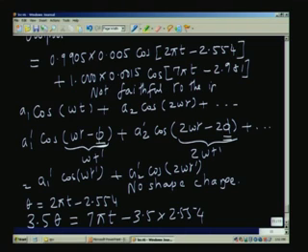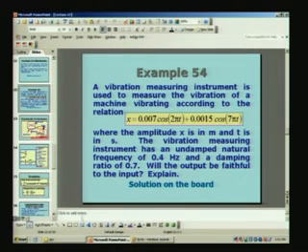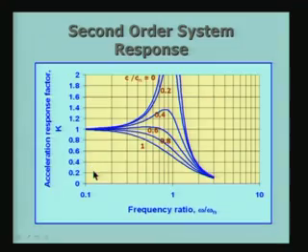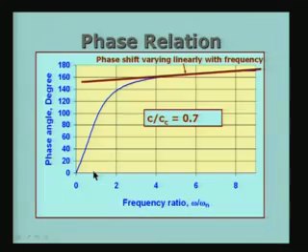And what I will do is go back to the response curve, and immediately you will see that it is in agreement with what we have already seen. If I look at the response curve, there is a factor of 3.5: omega by omega n is 2.5, and 2.5 is somewhere here, and the second one is somewhere here. Therefore, you see that now it is quite departing from that. This is the difference we are talking about.